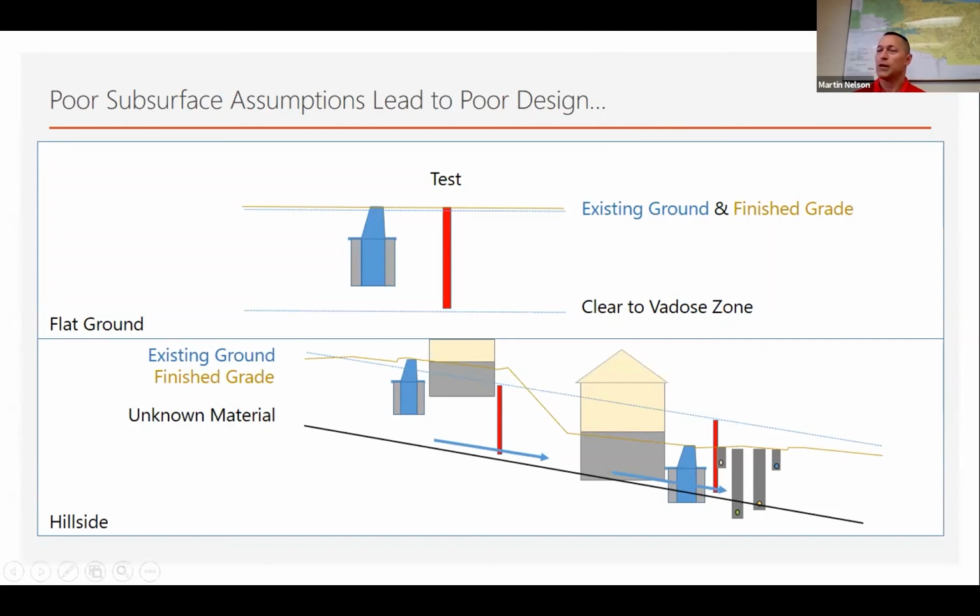So in addition to looking at the requirements in the Stormwater Management Manual, looking at cationic exchange, or looking at other site suitability criteria for certain structures, in addition to looking at what is down there, one of the City of Kennewick's requirements is to provide an infiltration trench at the location and depth of the infiltration structure and a soils log 5 feet below that. Well, that's not always enough. And in the hillsides and in these unknown areas, you really do have to do more.